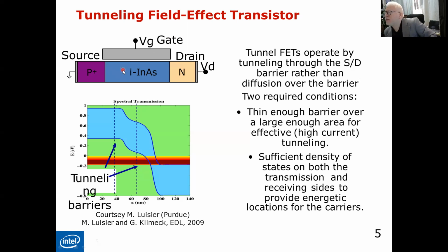The second is that in the MOSFET we have either a P substrate or an N substrate. However, here the substrate is intrinsic, or in other words, the channel is intrinsic. As you can see, here we still have the gate oxide and the gate. So let's first start to plot an energy band diagram for the PIN junction.